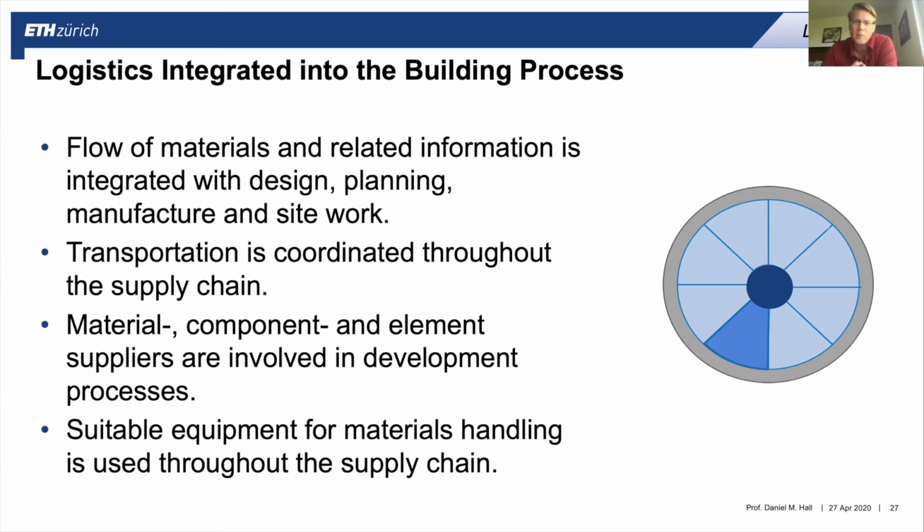You need to make sure that whatever you're designing will fit into the transportation systems nearby. Most often that means, will it fit on the back of a truck? If you've designed something too large for a truck to move for your market, then that's going to be a major challenge. You need to also ensure that material, component, and element suppliers can be involved in the development process, and that suitable equipment for material handling can be used throughout the supply chain. So do you have the right lifts? Do you have the right hooks so that pieces can be moved into the final location?